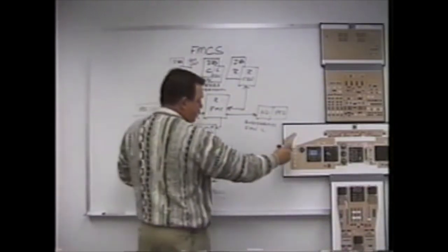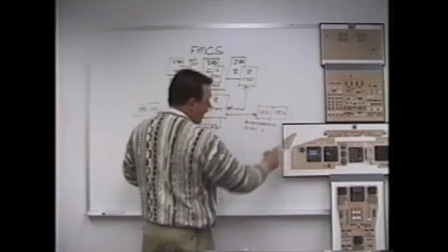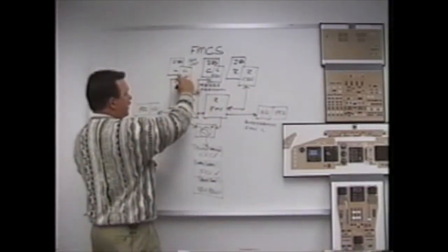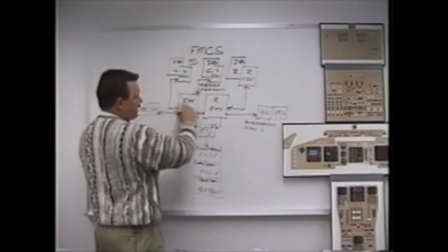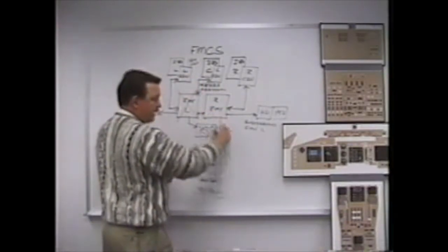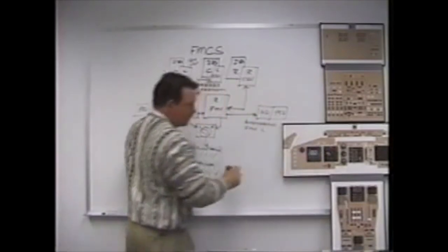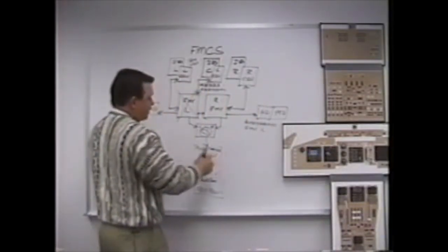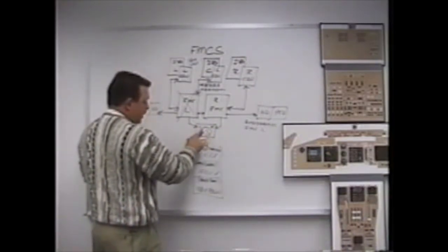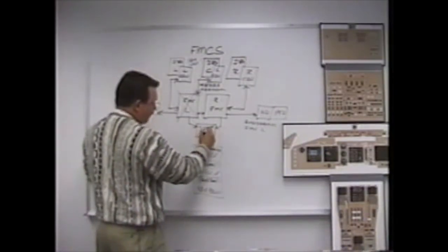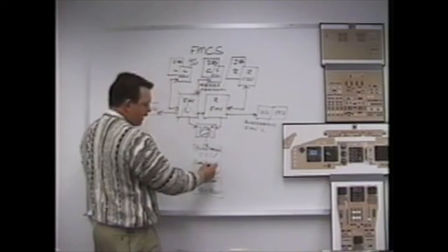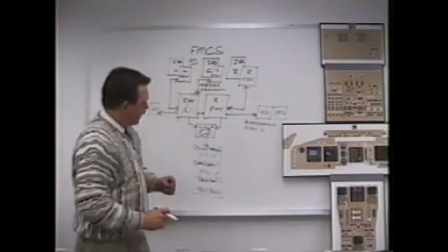So the first switch will have us move to the right FMC for the captain's display. What that will do is rewire the CDU, the PFD and ND over to the right FMC. As a result, the captain can get all of the information displayed back that the left FMC took away. The second switch we're going to move is this selector switch here. The procedure will have us move this to the right. And when we do that, we regain our signal flow to our auto throttles, to our LNAV and VNAV, and our auto-tuning of the nav radios.